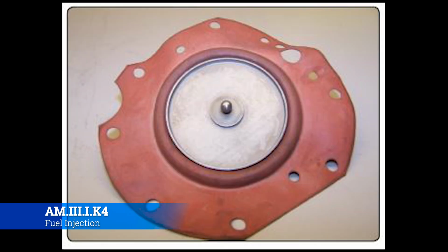Okay, the next component in line is going to be our regulator section. It consists of a fuel diaphragm, like the one that you see here, that opposes the air metering force. So fuel inlet pressure is applied to one side of the fuel diaphragm, and metered fuel pressure is applied to the other side. The differential pressure across the fuel diaphragm is called the fuel metering force. Now, the fuel pressure shown on the ball side of the fuel diaphragm is the pressure after the fuel has passed through the fuel strainer and the manual mixture control rotary plate, and is referred to as the metered fuel pressure. So fuel inlet pressure is applied at the opposite side of the fuel diaphragm.